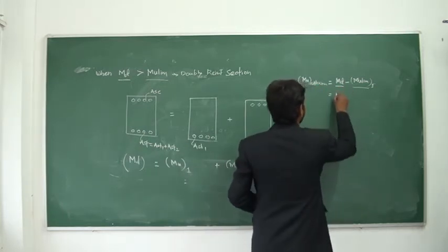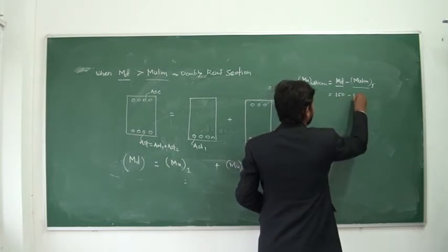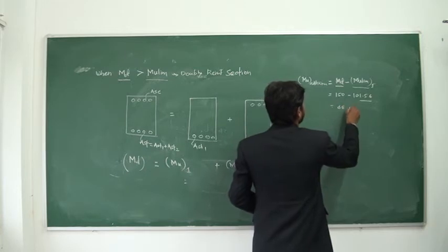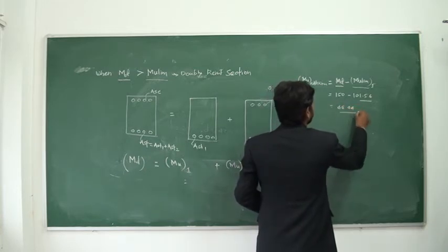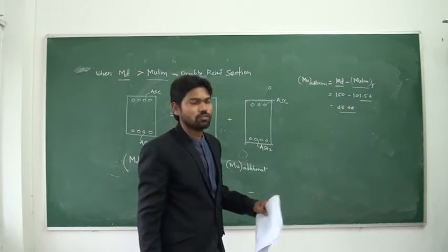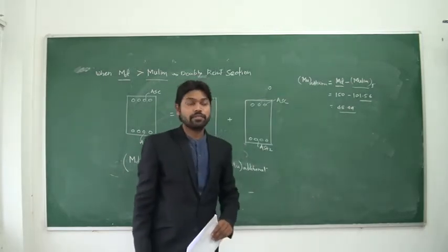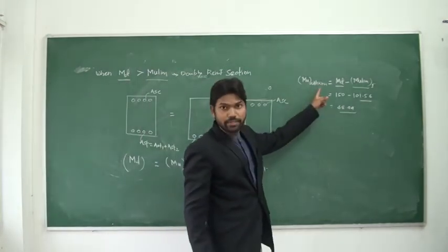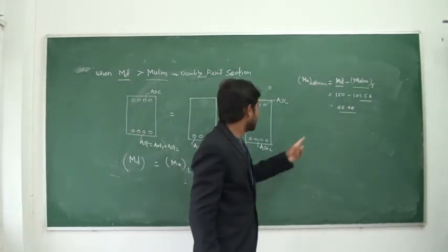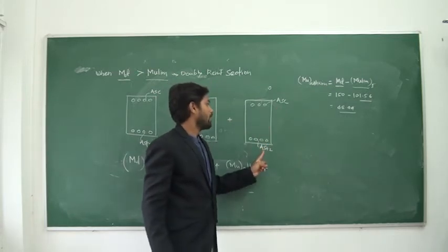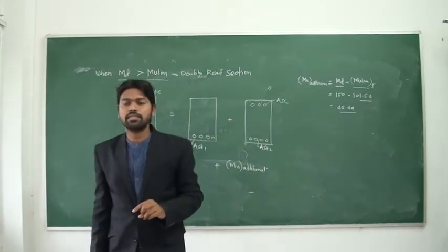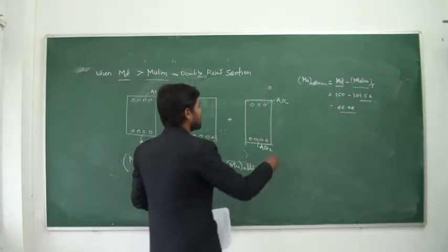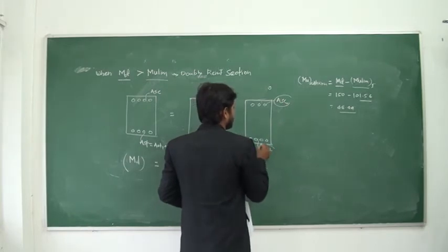This is the extra bending moment. Now for this particular previous case, this value will be something like 48.44. Okay, so this is the additional or extra bending moment which is there in this particular beam. Now who will resist this additional bending moment? This will be resisted by this ASC and AST2. Okay, so this additional compression steel and this additional tension steel.